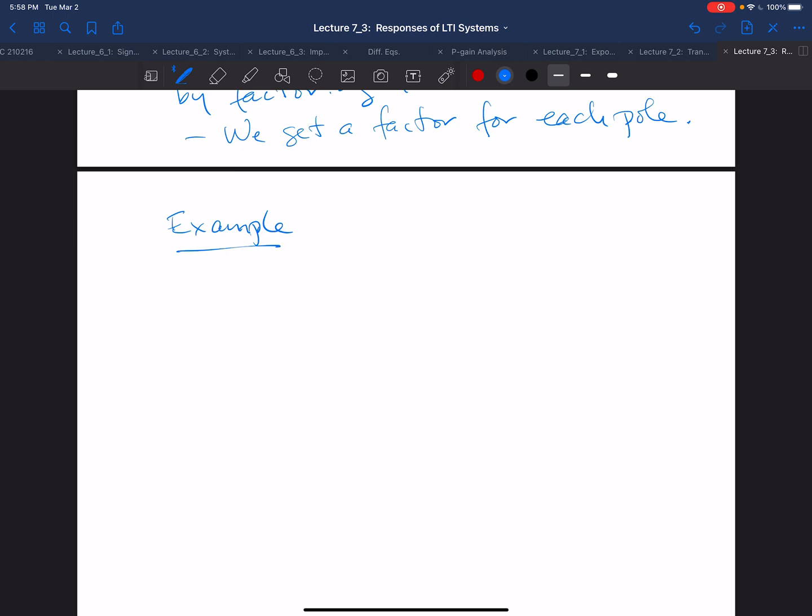So suppose we have a mass spring system with no damper. Then it might obey an equation of this form: m y double dot, the mass times the acceleration, plus the spring constant times the displacement equals an external applied force F. So let's suppose that we're perhaps interested in doing position control. So the output that we're interested in is the displacement y as a function of time. And suppose that the input of our system is going to be the applied force as a function of time.